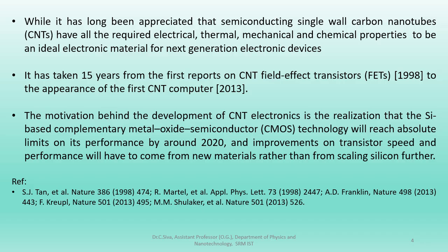While other high mobility materials like indium gallium arsenide have shown potential, they face integration challenges, especially for CMOS logic on silicon substrates. Silicon dominated because CMOS offered high noise immunity and low static power. But CNT CMOS could provide further gains by reducing switching energy and heat generation.